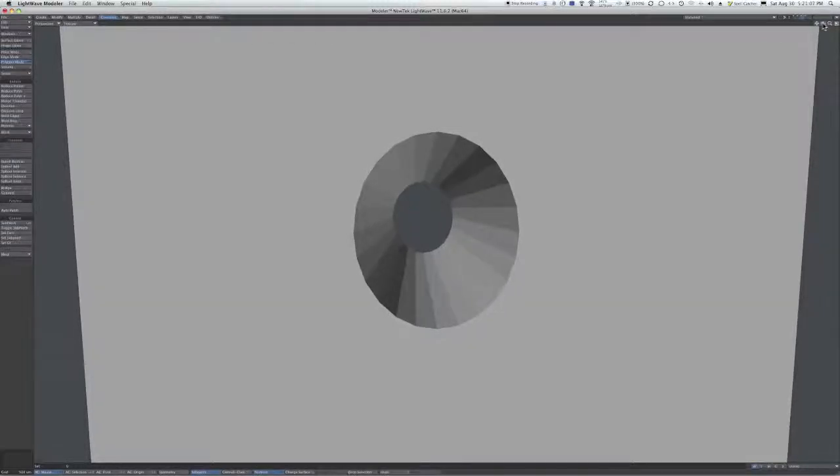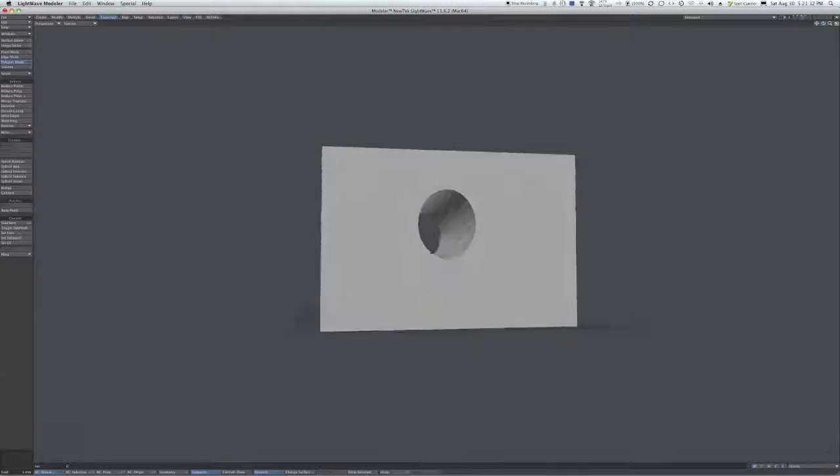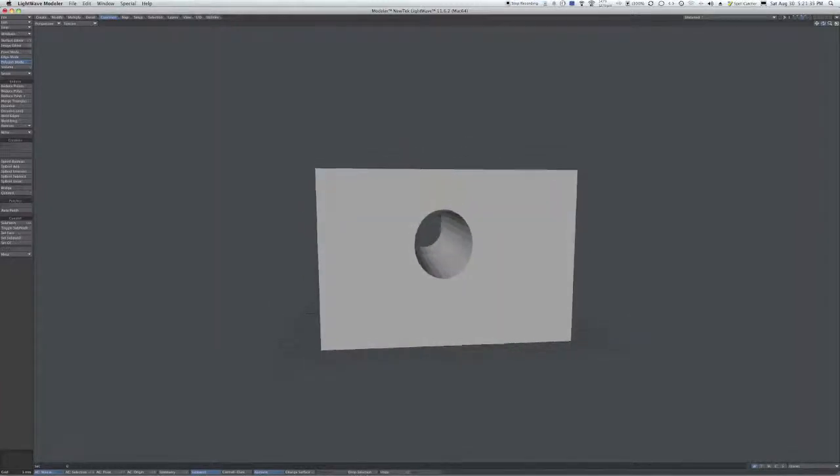Now there are multiple reasons for that. For one, you're making it with straight lines, and so you can imagine that the hole's on the inside, and every time a line goes straight, it actually cuts a little bit of a corner, so to speak. It would be like if this was part of your hole, it's a line from here to here, so it cuts the corner. That makes it smaller.